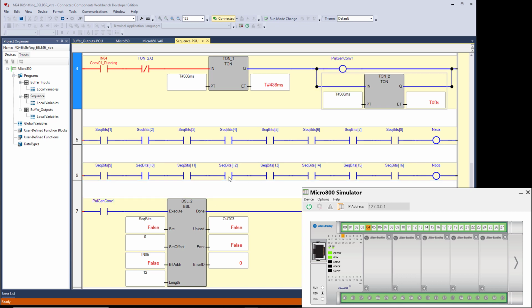That means that the bits are going to get pushed into sequence bit 1, and when they get pushed out of 12, they go into the zone. They don't use 13, 14, 15, 16, and all the way up to 100. Remember, sequence bits, that's an array of 100 elements, 1 through 100. We're only using a section of that array of Boolean data types in memory.